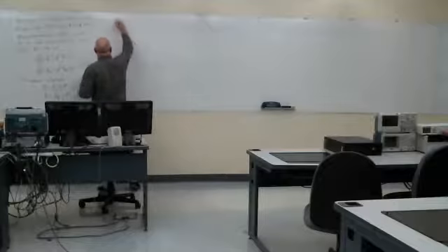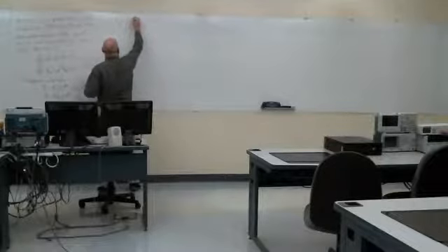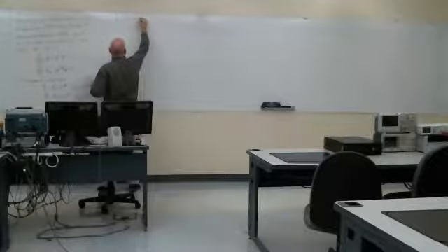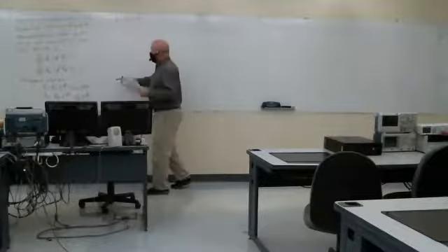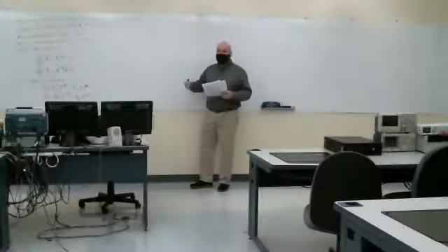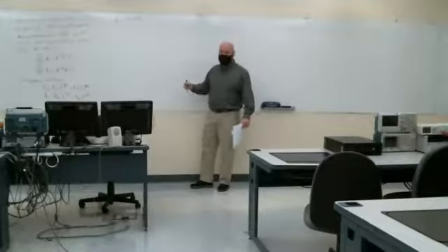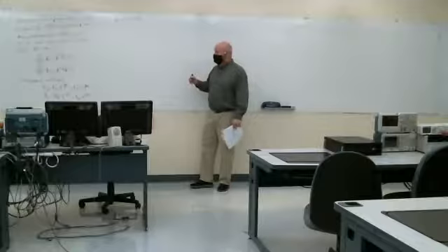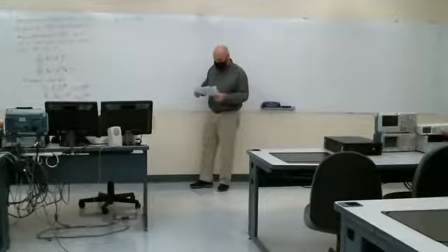And again, our general phasor would be EX x-hat plus EY y-hat. So this is the vector, and then these are functions of z. They're only functions of z at this point. They're not functions of time, again, because they're phasors, and because they're plane waves, they don't have x and y dependence.